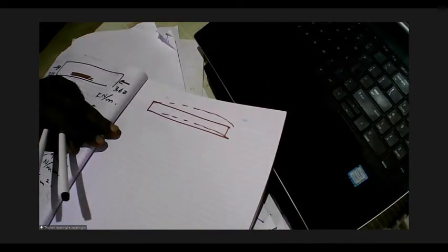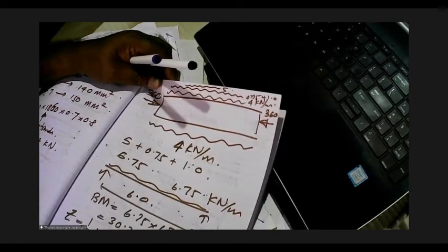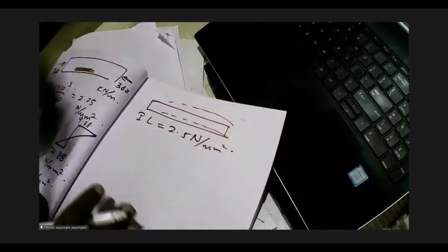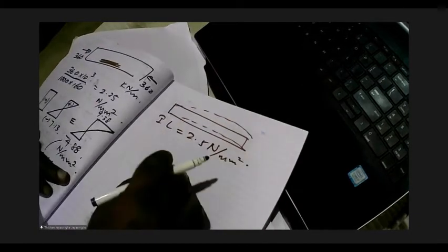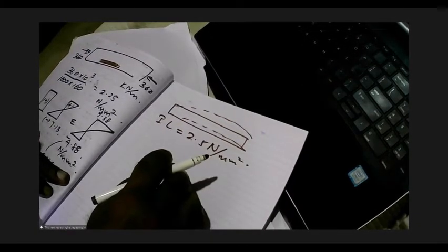So what I have done is, I have tried to see whether only the weight can be compensated. Cannot do that. So that means I have to go for a higher pre-stress. I cannot compensate only the weight, because this slab is heavily loaded. It's loaded with a 5 kilonewtons per meter square load. It's a crowd loading. But what will happen if the imposed load is only 2.5 kilonewtons per meter square, like in an office building?